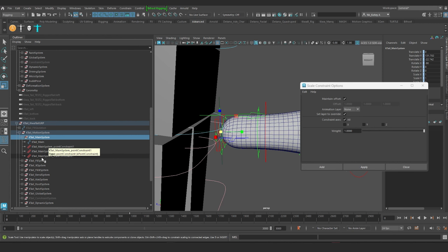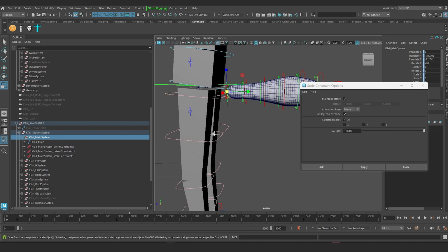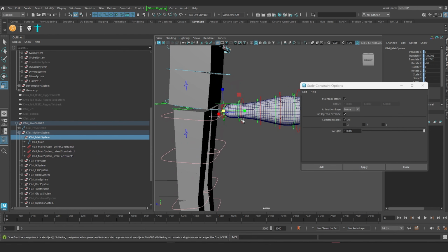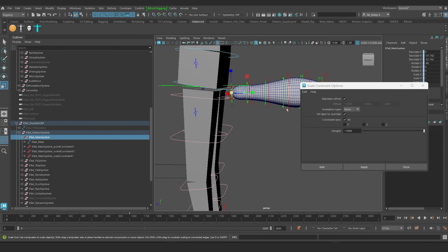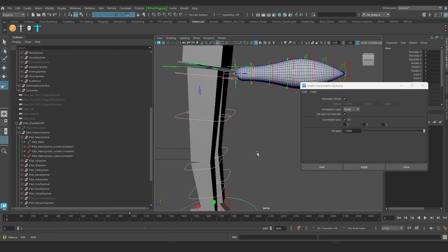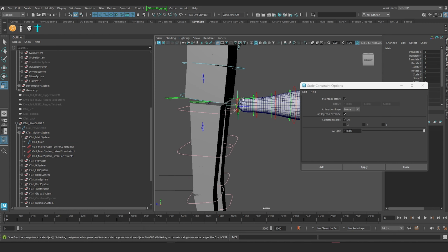So I tried to use that to attach it to my rig in the various ways in which it's supposed to be attached. So there's two locators here. One locator is parented under the root, the other is parented to the global control, and constraints are applied from the locator to the tail's global control in ways that allow the tail to follow along with the body.